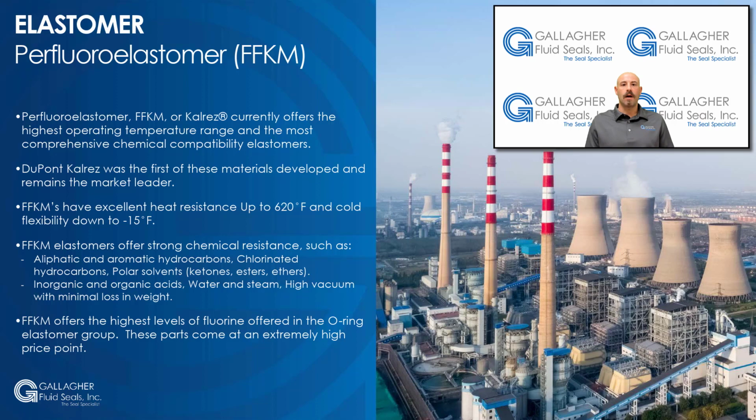FFKM elastomers offer strong chemical resistance to the following: aliphatic and aromatic hydrocarbons, chlorinated hydrocarbons, polar solvents such as ketones, esters, and ethers, inorganic and organic acids, water and steam, and high vacuum with minimal loss in weight.